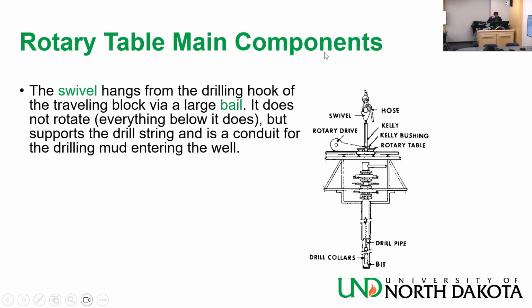And the first joint, because you know the drill string is cylindrical, right? It's very hard to rotate something cylindrical. How do you apply torque to something cylindrical? So we have a very special joint at the very top of the drill string, and it's always that joint.